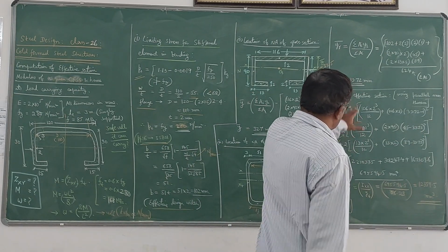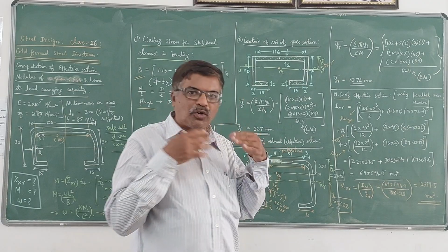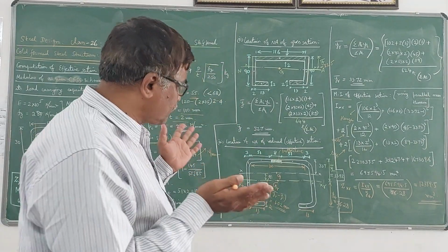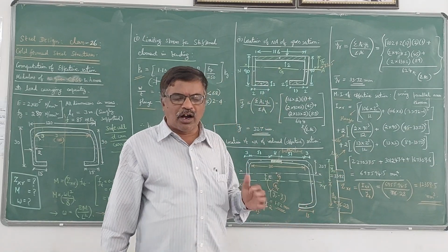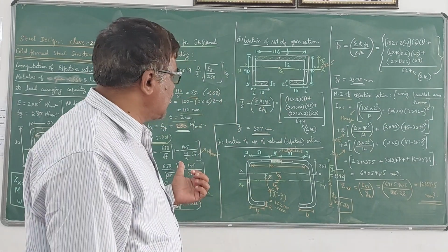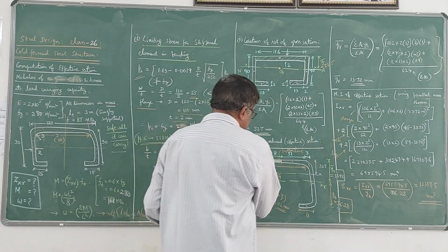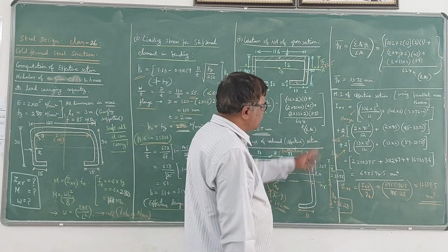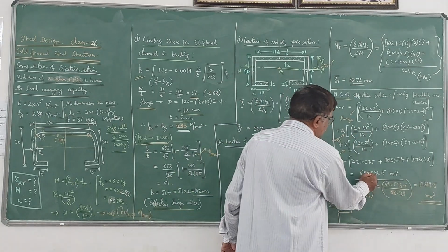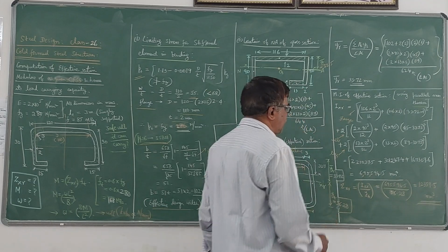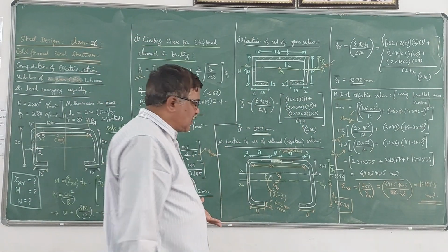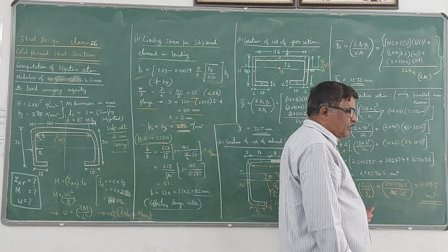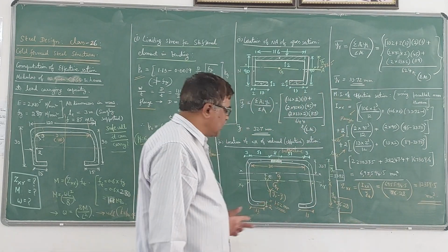Now these are the moments of inertia of the three portions separately, and we have to add them to get the total moment of inertia of that reduced or effective section. With respect to this XR axis, IXR, after simplifying, becomes 695,594.5 millimeter power 4.